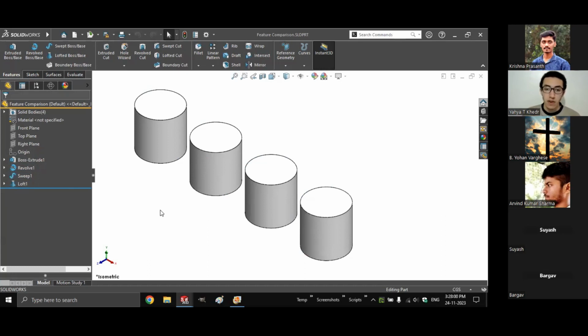So for example, if I was given a diameter, and now I'm working with a revolve, so I've got to divide that by 2 to make a radius, for example, or I might add a dimension as a full diameter in my sketch if that's something I want to do. So all of this processing must go on inside of your mind while you're going through the model, and this is the best place to take a deep breath and start thinking of the best feature to use in that case.